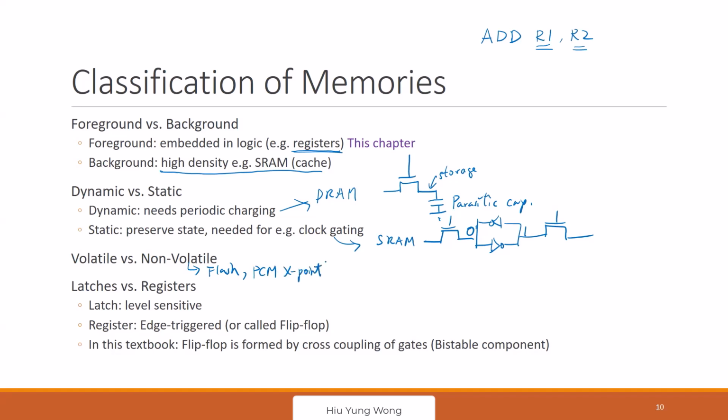They are non-volatile. And I also have an article of the day about magnetic RAM. They are non-volatile, and they're very close to SRAM in terms of speed. That's cool. I can hold the whole block and turn it on immediately. Right? And of course, we have something called resistive memory. Hopefully, it will be useful in the future. These are the non-volatile memories. It means that even if I remove the VDD, the content is still there.